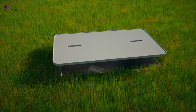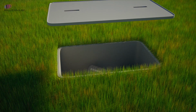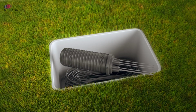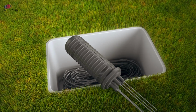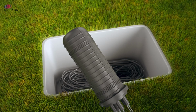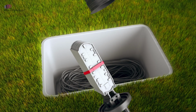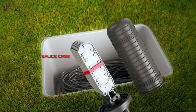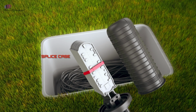Handholds are used to store slack and splice cases. Slack is extra fiber that can be stored inside a handhold. It allows for easy repairs and maintenance to a network. Splice cases are used to protect bare fiber after the cable is spliced. Splicing fiber connects two cable reels together or drops fiber off in a different direction. Splice cases can be found in both underground and aerial networks.